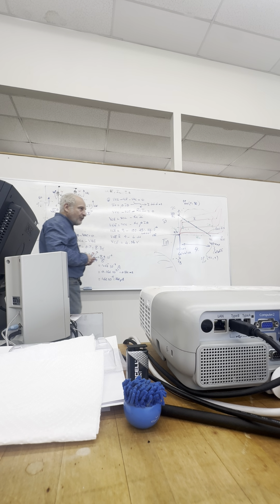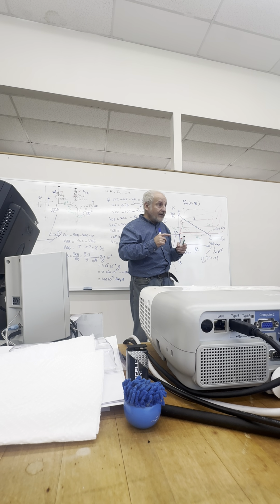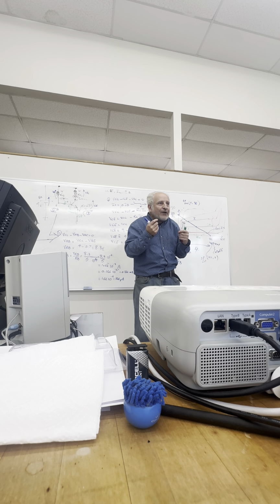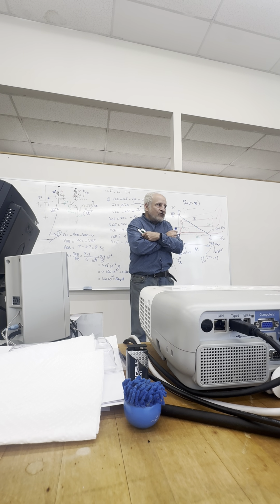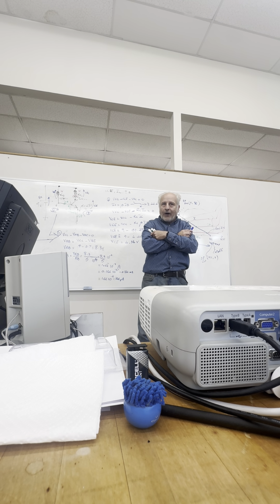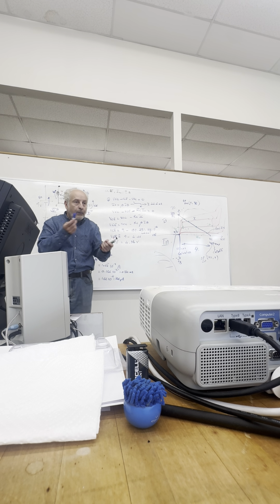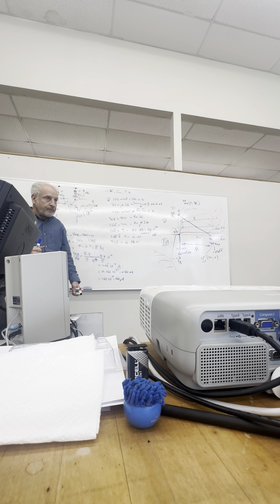Right? This is what we want, VB, and you've noticed RBs are usually much higher in scale than RCs. Look at your circuits. You get to see that trend where RBs are hefty. The reason is because they want to keep the current as low as possible. Does that make sense? Because you're just using the current for control. That's all you're using it for. It's not to drive stuff. Well, yeah, it is because it moves up and down, but the real current that's usually connected to the load is IC, or sometimes IE. So far, so good? Okay, good.